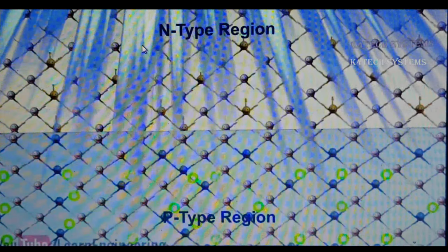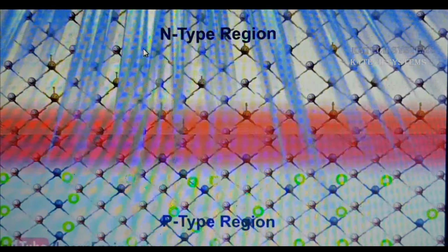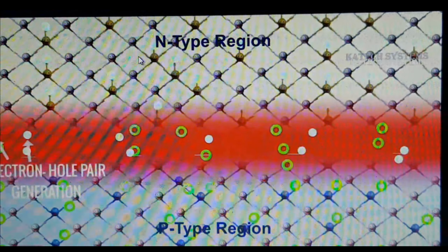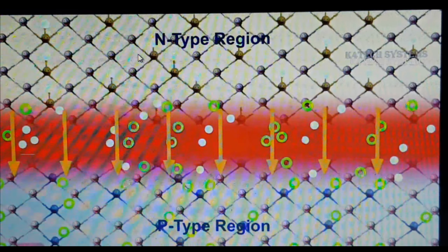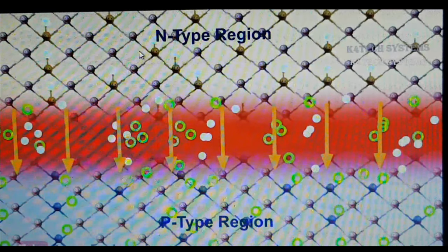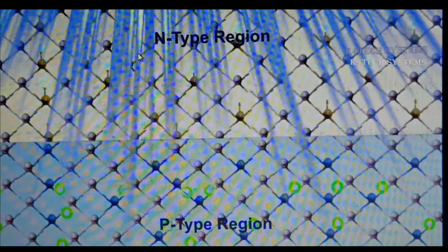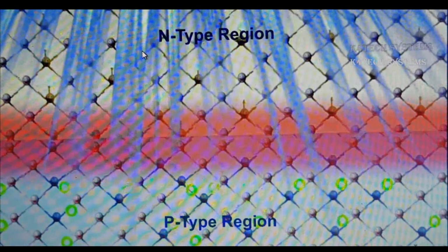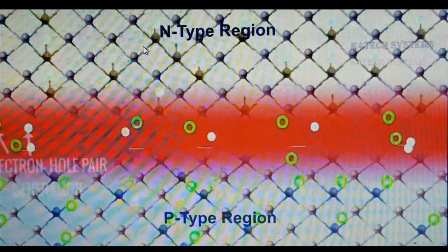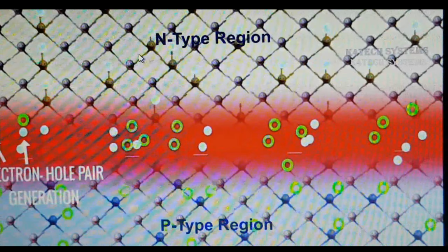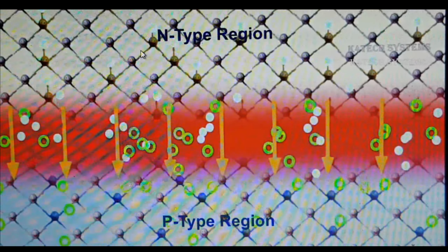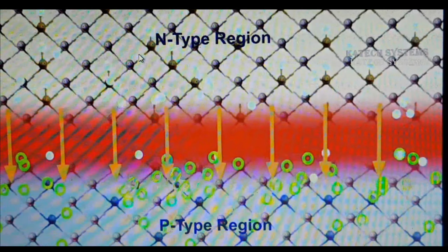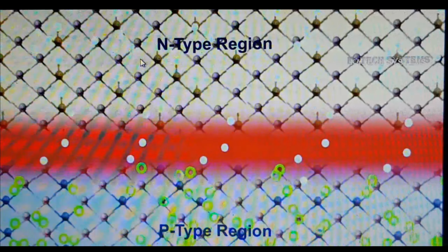What happens when solar light strikes the solar cells? To tell it clearly, when solar light strikes the p-n junction, light hits the n region of the PV cells and reaches the depletion zone in the p-n junction. This photon energy is sufficient for moving electron-hole pairs in the depletion region. The electric field in the depletion region will make electrons escape. This will drive the electrons and freed holes outside the depletion region. Thus, electrons are concentrated in the N region and holes are concentrated in the P region. Their concentration will become so high that a potential difference develops between them. Thus, it works like a battery.